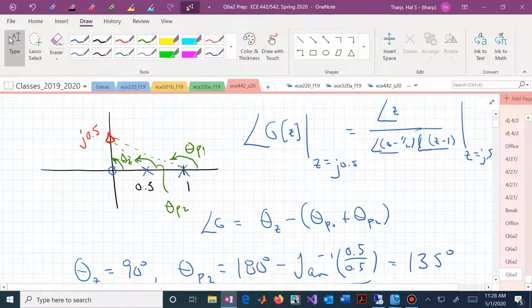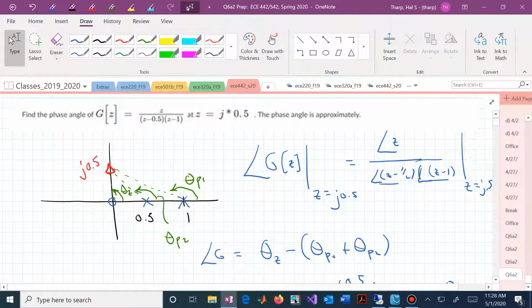It's now minus 198, so we need to not take so much angle away through the poles, or if we started to slide that point up vertically on the imaginary axis, and if we slid that point up in a manner that maybe allowed the angle of theta P2 to be about 10 degrees smaller than 135, and theta P1 about 8 degrees smaller, then we would have an angle at that cloud location of minus 180. Oh, and now that spot is on the root locus.